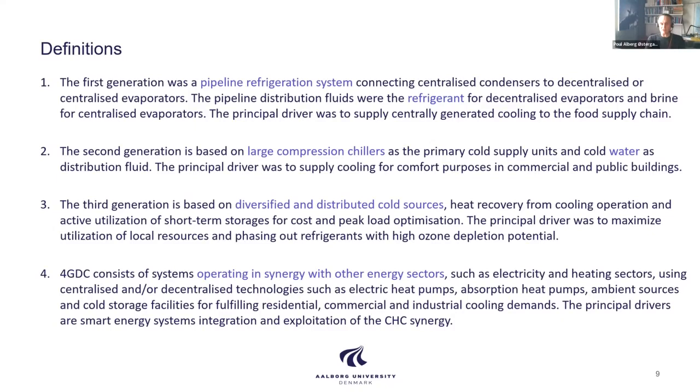So the first generation, that was the pipeline refrigeration system with refrigerant. So you're basically distributing something like a CFC gas. For the remainder, it's all water-based. We have the large compression chillers in the second generation. We have the diversity in the third generation.